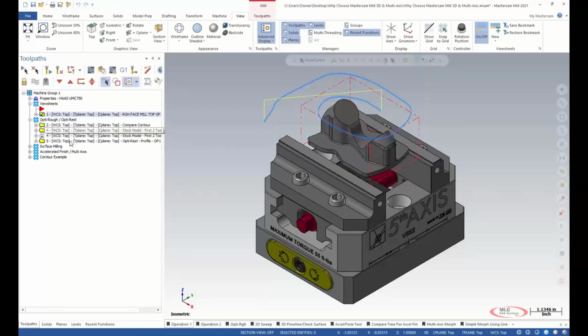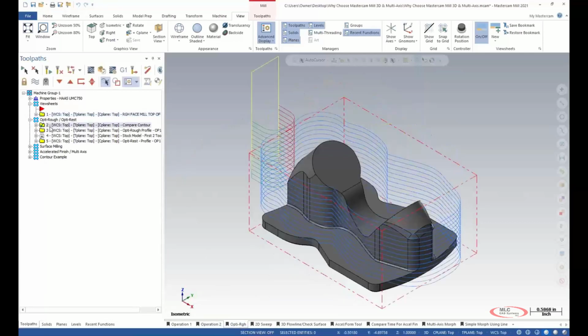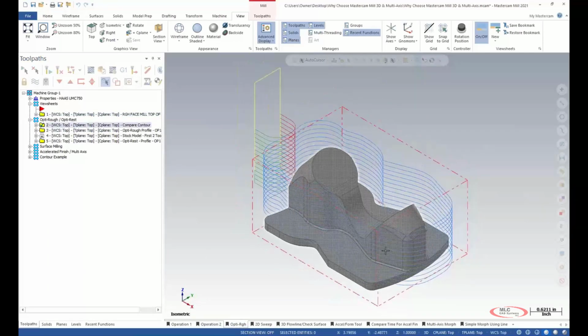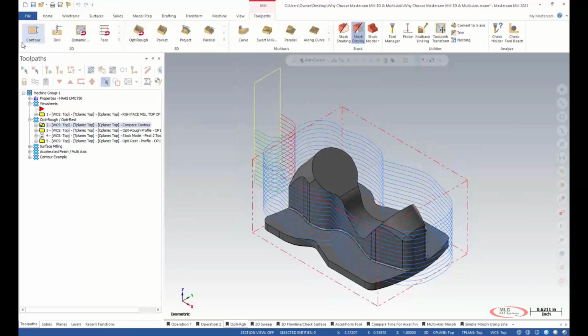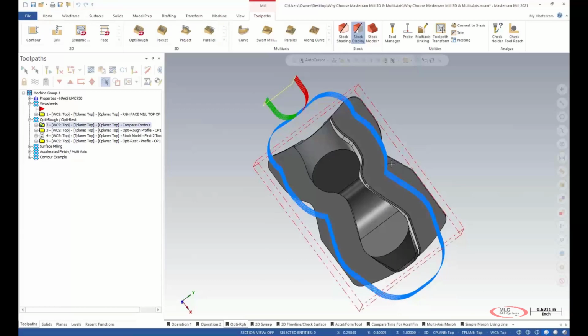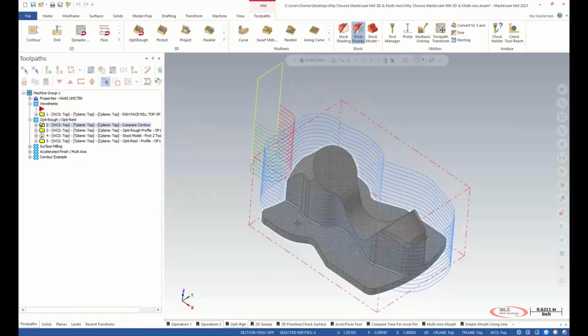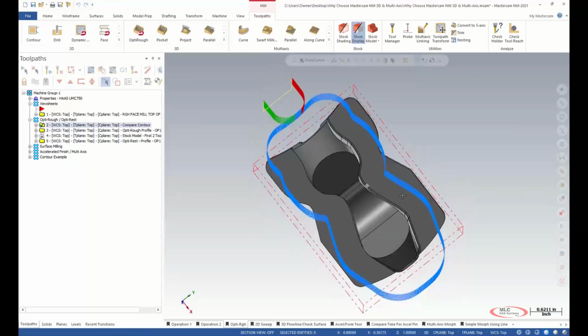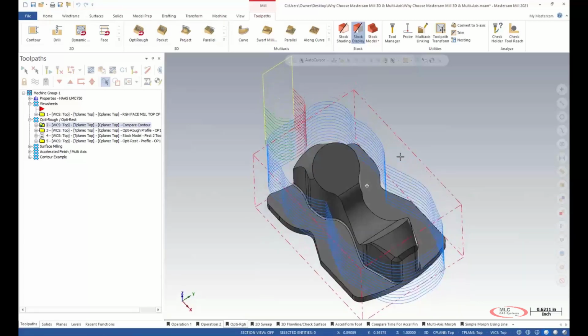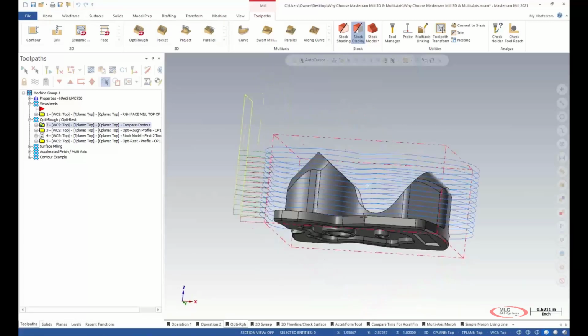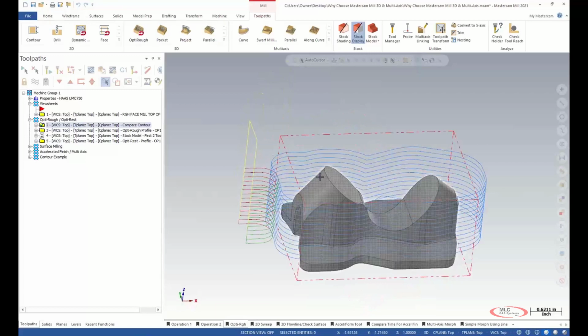So in a sense, looking at the regular toolpath that I would have using my 2D toolpaths for a contour, you can use a 2D dynamic as well, but I'm only allowed, whether I'm using contour or dynamic, to cut the profile of this part. Afterwards, you would have to most likely create a ton of geometry in order to get this shape out.